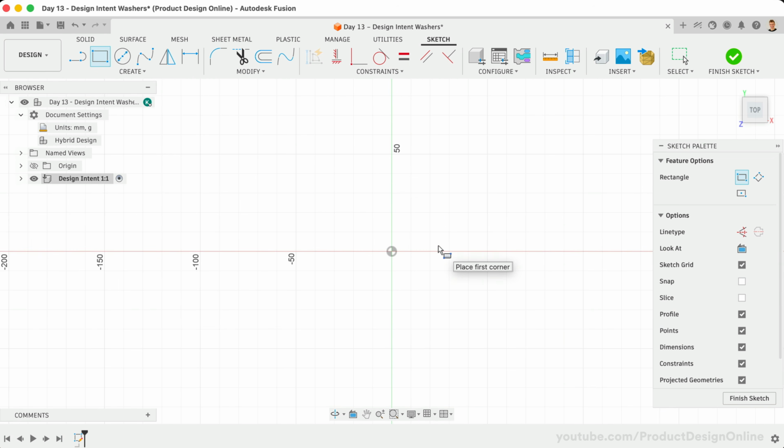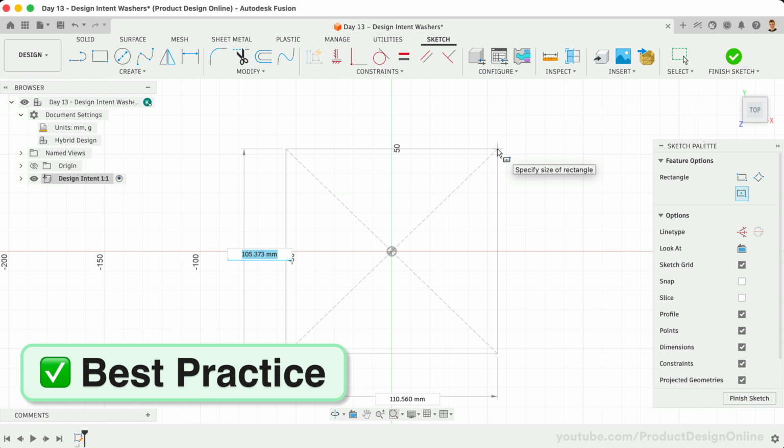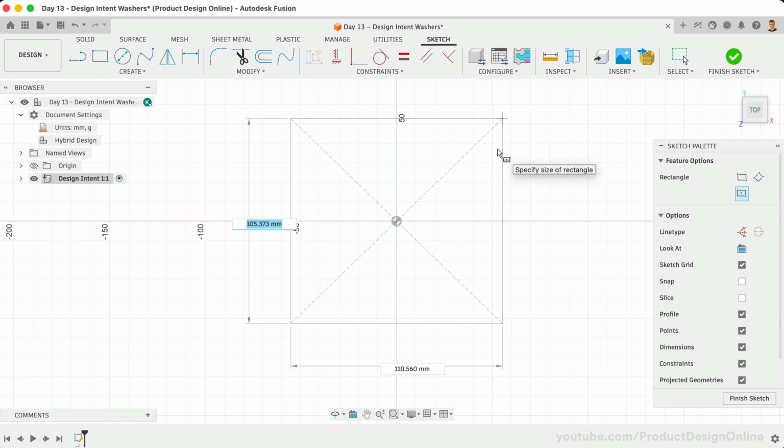on a table. Let's also switch to the center rectangle type in the sketch palette. This option allows you to center the rectangle to the origin point. Remember that starting at our origin point is a best practice. Anchoring your sketch to the origin is crucial for fully defining your geometry, preventing unintended shifting, and creating a predictable foundation for your 3D model.